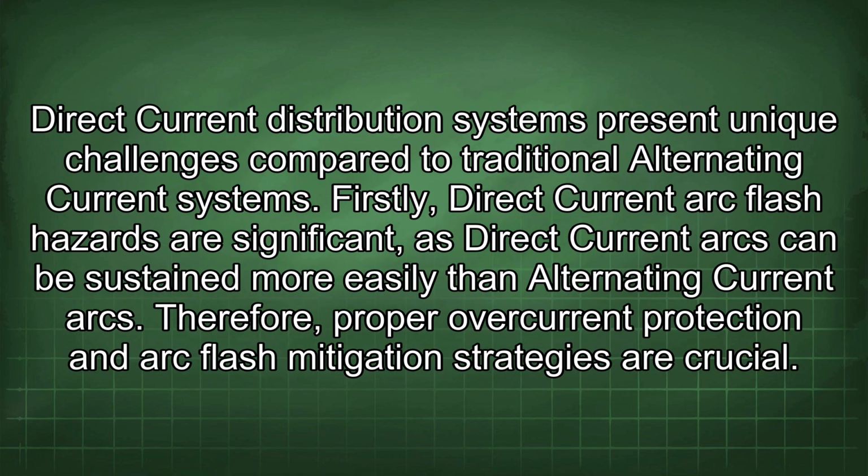Direct current distribution systems present unique challenges compared to traditional alternating current systems. Firstly, direct current arc flash hazards are significant, as direct current arcs can be sustained more easily than alternating current arcs. Therefore, proper overcurrent protection and arc flash mitigation strategies are crucial.